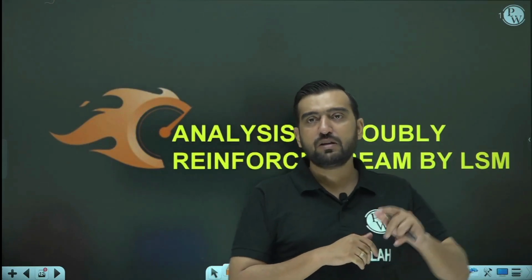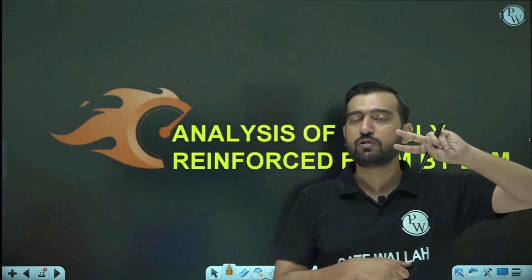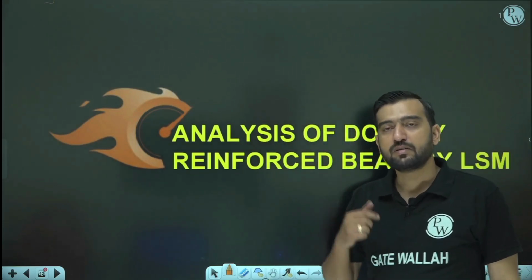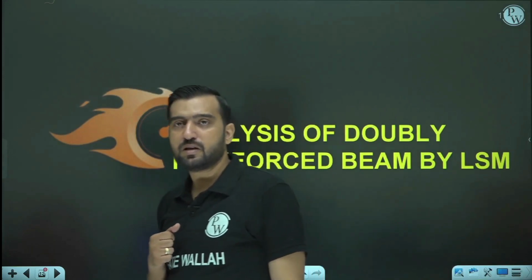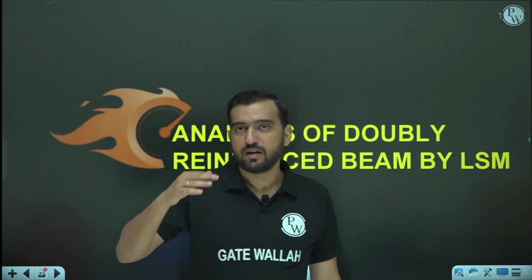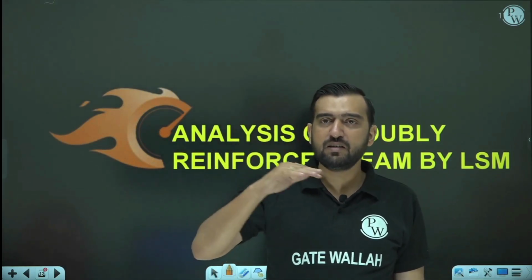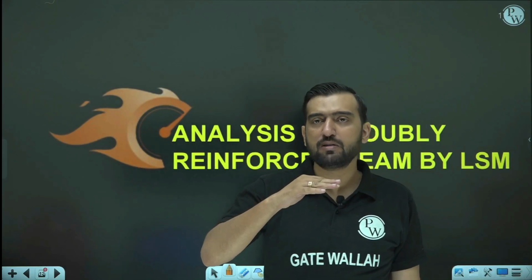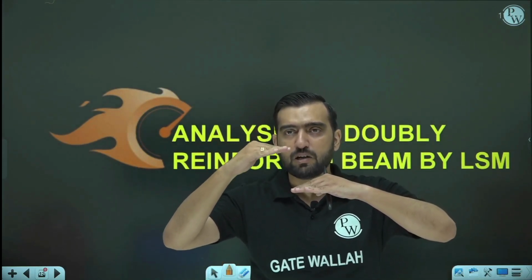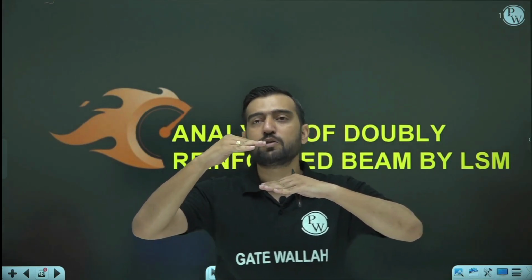So now the compressive forces of steel along with the compressive forces of concrete are going to challenge the tensile strength of steel. Okay. And one more thing, you can also think of it in this manner. If you are increasing the amount of steel on the tension side, then XU is coming down. A time will come when AST is corresponding to the limiting condition.